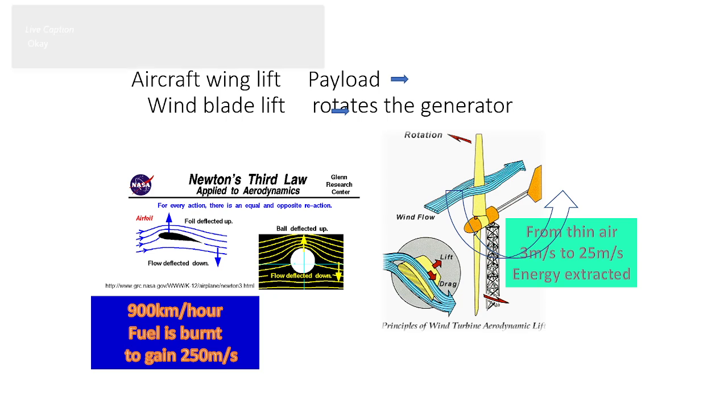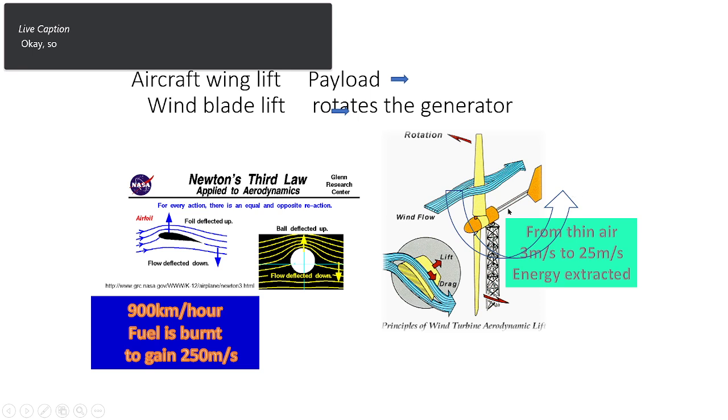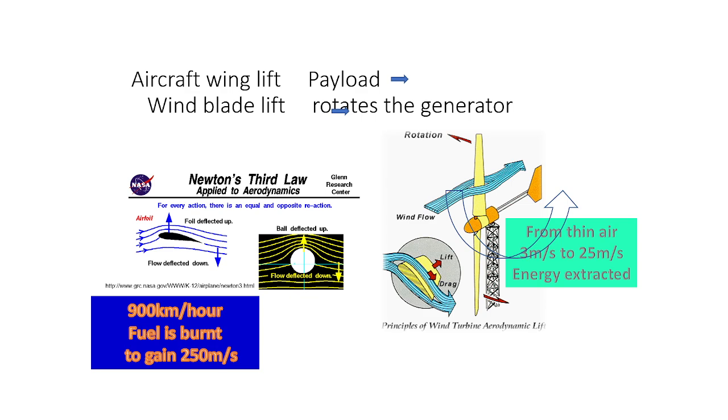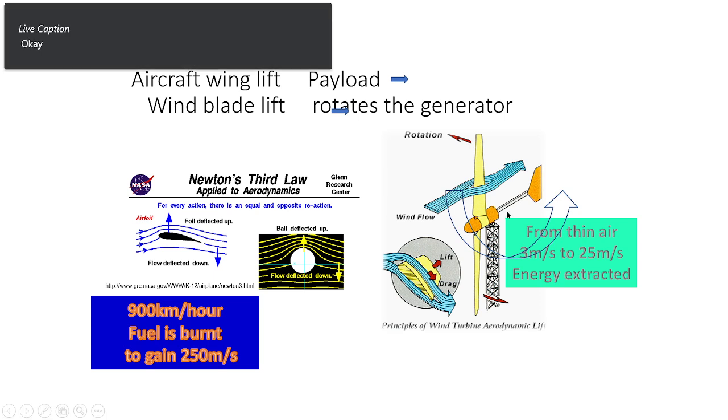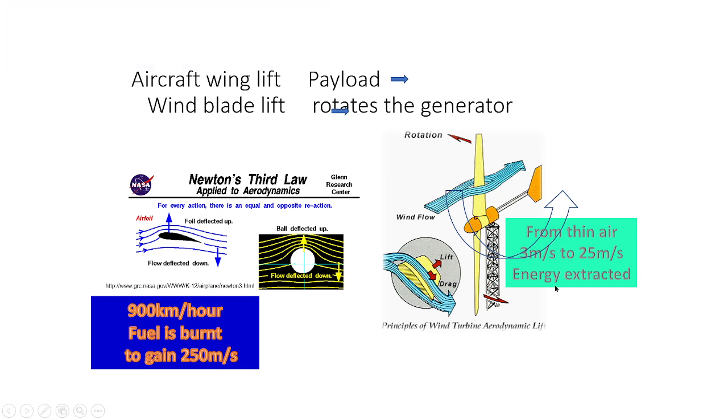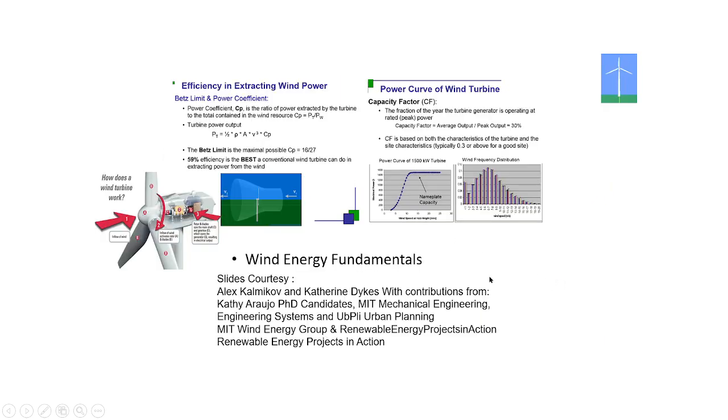Similar to that, you first go out of wind by changing the pitch angle in such a way that it becomes a smooth aerofoil to allow the wind to pass through without generating any lift. And whatever is the extra thrust load that is coming on the tower and the blade, it will resist by standing still. That is called cutout wind speed. And in between there is one which is called design or rated wind speed. So that is what is shown in this picture.